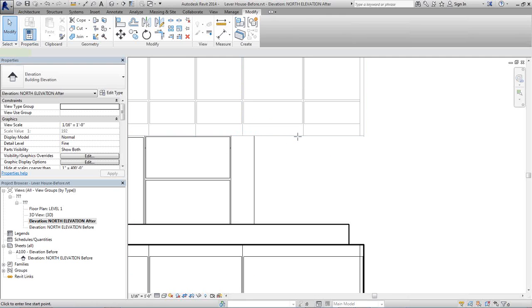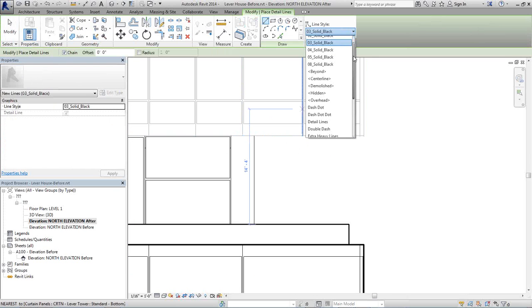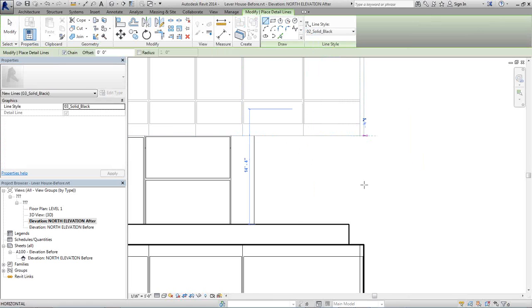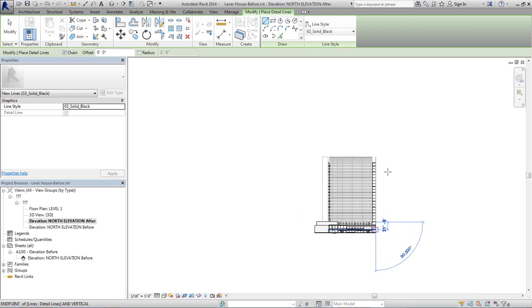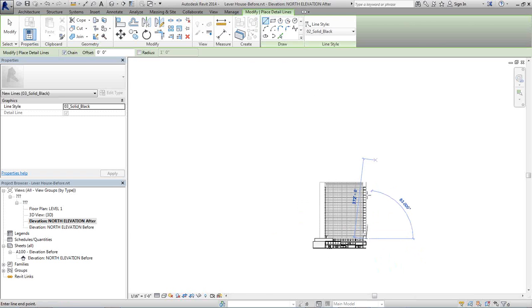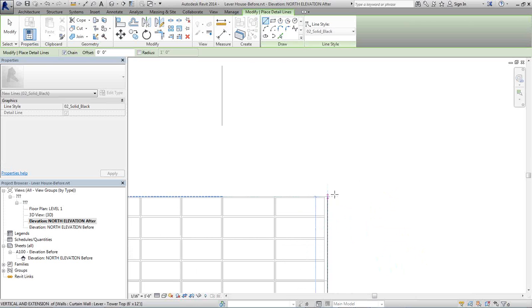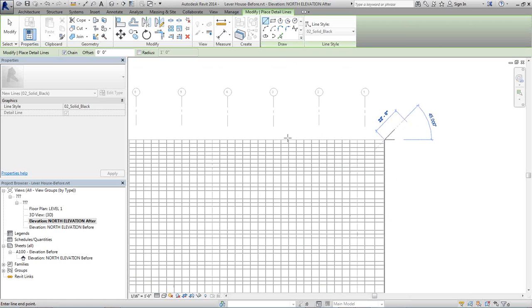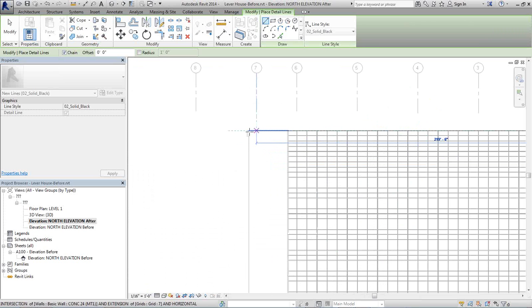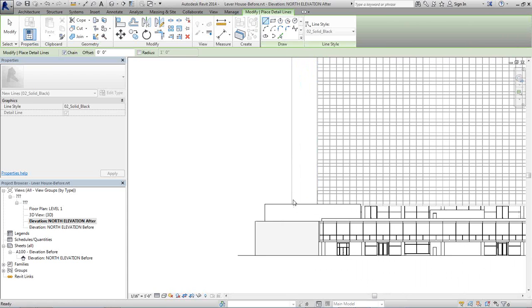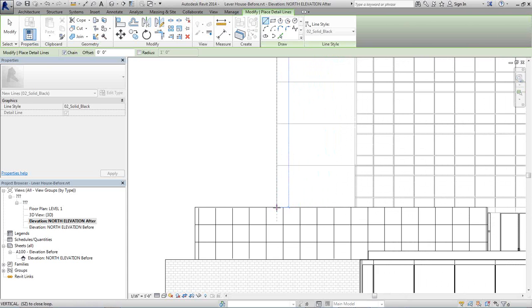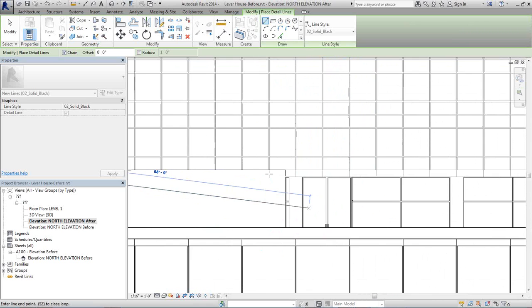Now I want to use detail lines again. And I'm going to use the 2 line weight to show how you can manipulate this. Looks like I zoomed out too far. So we'll just quickly draw this around. Because, essentially by making everything halftone, it's making all these lines both thin, but then also essentially gray. So we want to have a little bit of line weight, a little bit of black, right? A little bit of black on these guys.